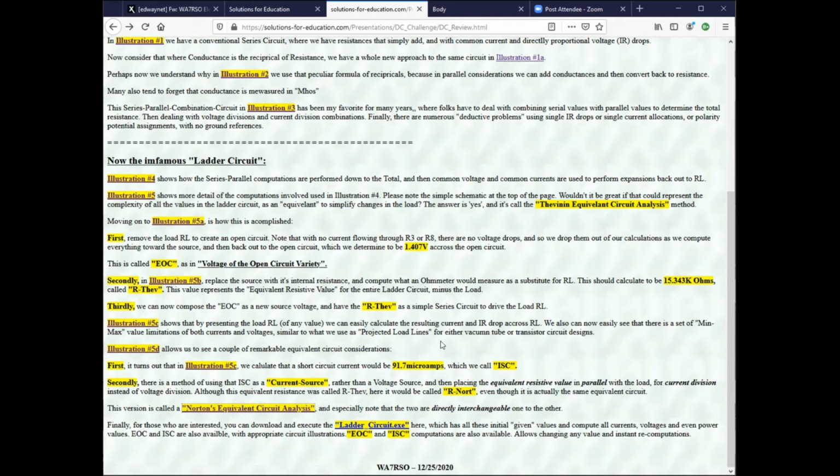What happens is there's two different ways of looking at the same thing. I'll give you an example why this is so important. When you get into, let's say, transistor circuit design, there's three different configurations for a transistor, as an example. Same thing as with tubes. You have a common base, common emitter, common collector. The characteristics of that transistor vary considerably depending on the way you structure it. As it turns out, a common base transistor has a constant current configuration, whereas a common collector, which becomes an emitter follower, is a common voltage device. So it really is a voltage source, constant voltage versus constant current.